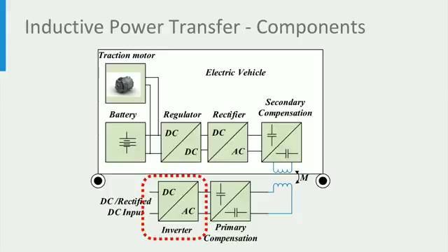The standard for electric vehicle charging earmarks a small band between 80 to 90 kHz for wireless charging of electric vehicles, with a center frequency of 85 kHz. The inverter produces this 85 kHz pulse-width modulated, or PWM, voltage, which is fed to a wireless charging pad. A charging pad consists of conducting coils spread over a surface in a specific shape and may or may not have magnetic material.